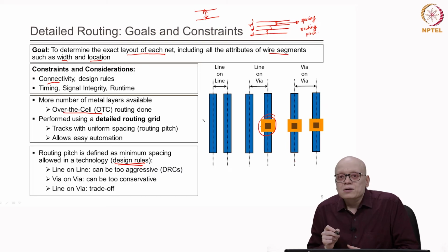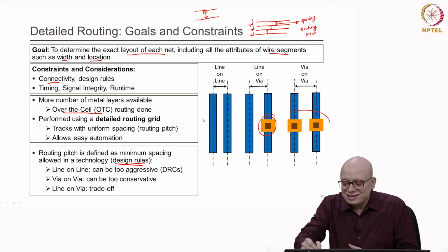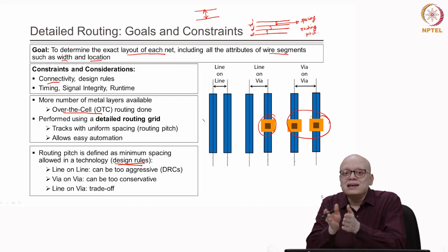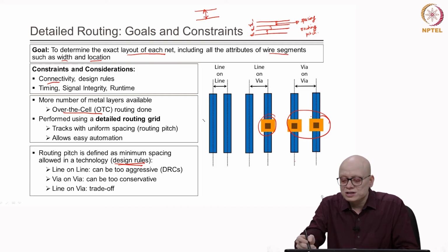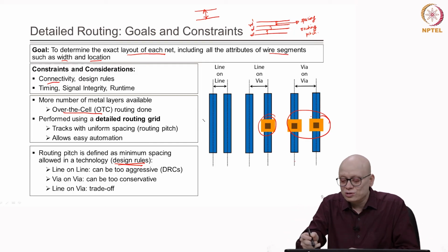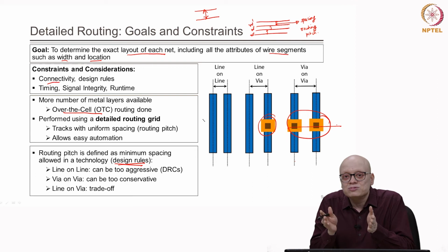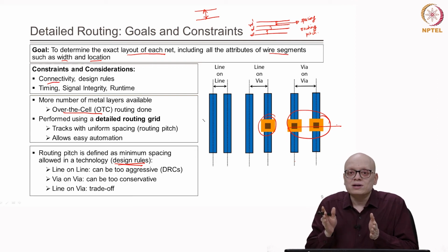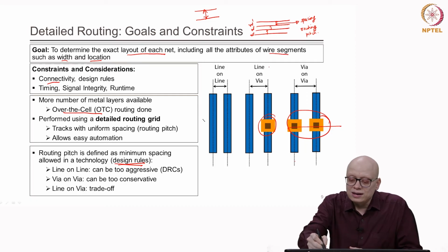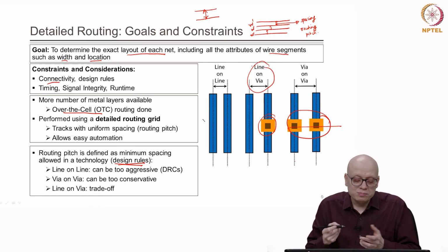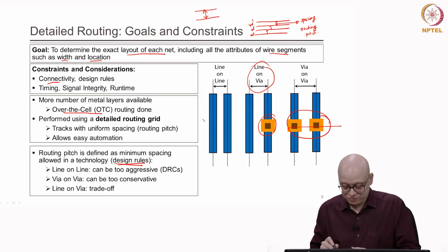But when we need two vias, like in this situation, we can either skew them in space or leave one extra line. Those situations where two vias should be exactly at the same horizontal space may not arise too often, and therefore this line on via spacing may be more optimal, or is maybe a good trade off.